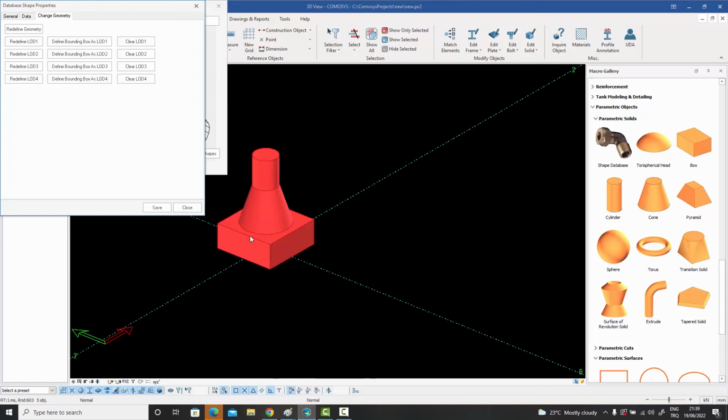And you can also create primitives for those drawings as well. So you can go and define that when I'm at LOD1 level, I just want this whole thing to look like a box, and you can create a box in this redefine. There are also some easy features. If you just press this one, it's going to convert it into a bounding box at LOD1 level.